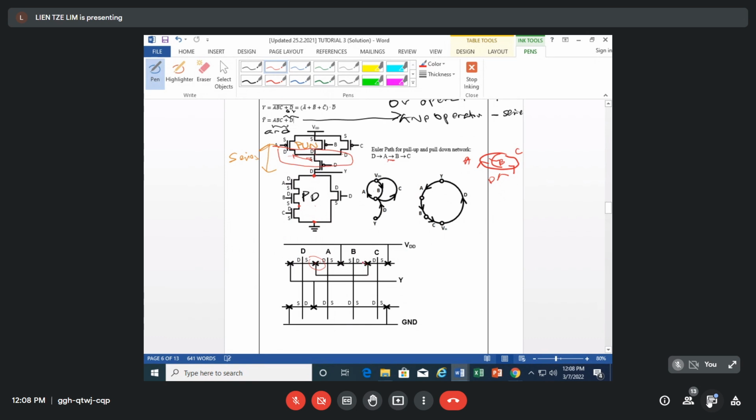And then here D is the drain terminal for both the transistors with inputs B and C. So at this node there are four connections from four terminals, and it should be drawn in this way. These two terminals are connected, and they are also on the same node as another terminal. That's why you see this contact and this contact connected together through the two contacts.